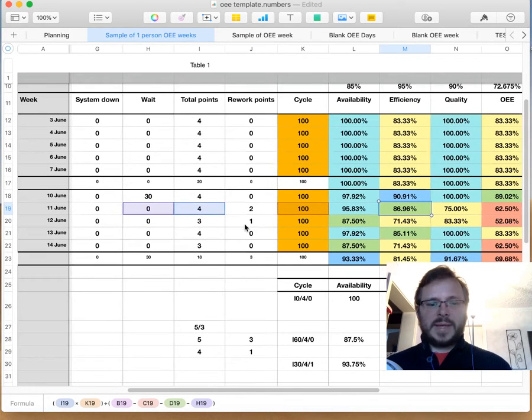The efficiency is again a little bit similar. It is the total points multiplied by the cycle time, i.e. the productive time in the day, divided by all the maximum time available minus all the other things that could have changed that availability. So the total time that was actually hands-on working divides the time, the produced results, so that we can see, if there was 400 minutes of produced time, for example, productive time was 400 minutes. We know that we, in theory, can't get to that 100% productive, but of that time, how much of the time we had available in the day was used. So we know that it's slightly less than that, and that was 86% in this case.